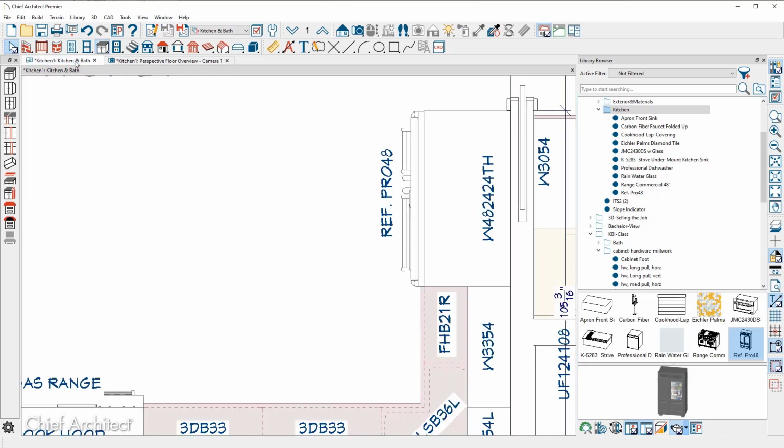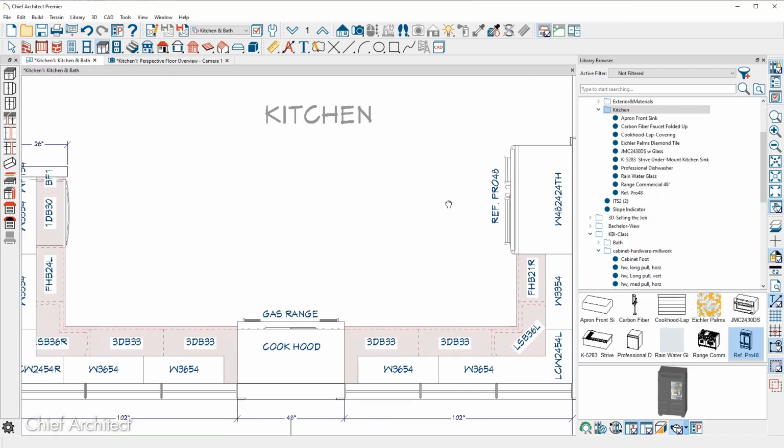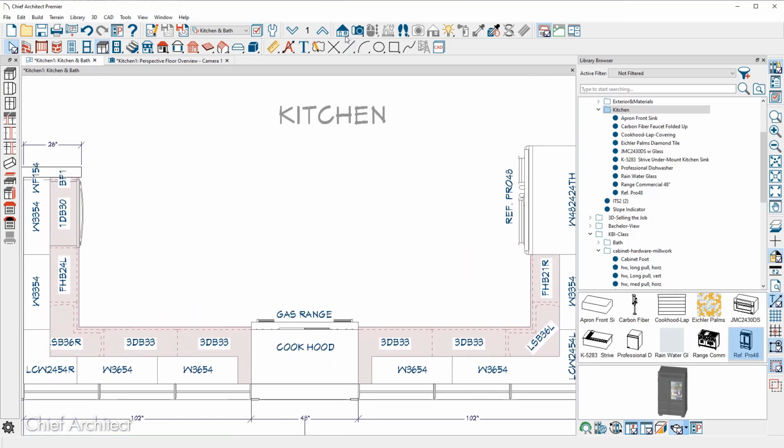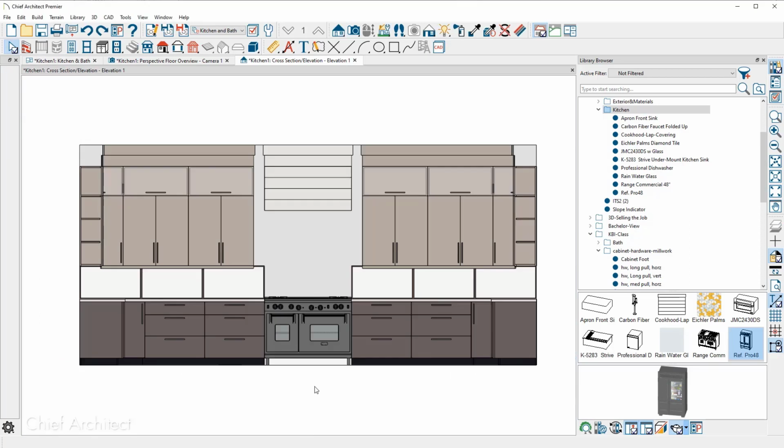The way that you create a wall elevation, zoom out so we can see the floor plan. Underneath the elevation cameras is specifically a tool for the wall elevation, and this is going to show you the wall restricted to the room that you're within, and also remove the platform information for the floor, the walls, and the ceiling.